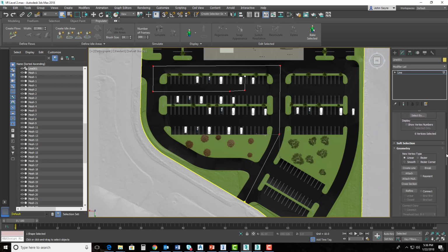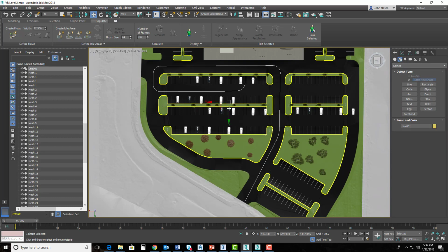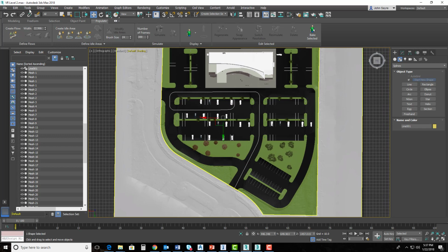We'll scroll down here in our editing dialog, and we will select Fillet. Now, I'm going to hold my left mouse click down over these arrows and push up, and you can see it's adding curvature to my PVIs. I just get it to where I want it, let off, and hit escape, and I can select the plus sign here, the create button, and it releases that line. I'll go ahead and save. I like to make sure that I save my line work. If I do something I don't want, I don't have to create it again.